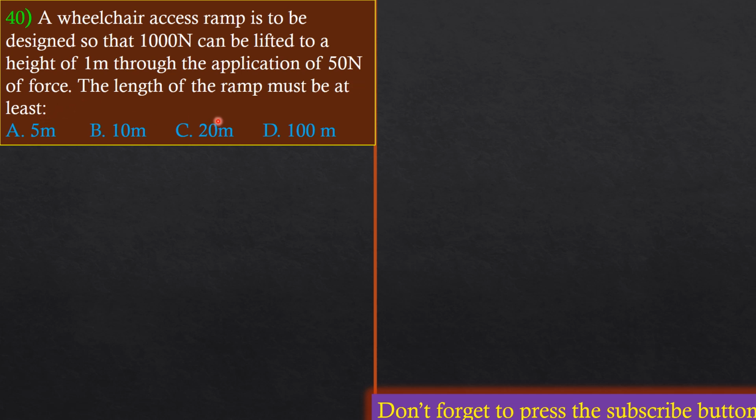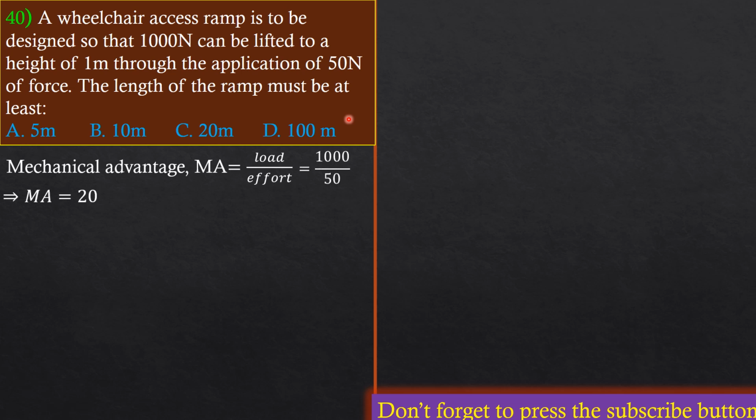So guys, let's simply recall for sure that we need to start by getting the mechanical advantage produced, and as well, guys, we have to use the concept of mechanical advantage, linking it when it's been applied on a ramp. The mechanical advantage is simply given as load over effort. As you all know, the load is 1000 newtons and the effort is 50. To simplify, we have mechanical advantage to be 20. It's a unitless variable.